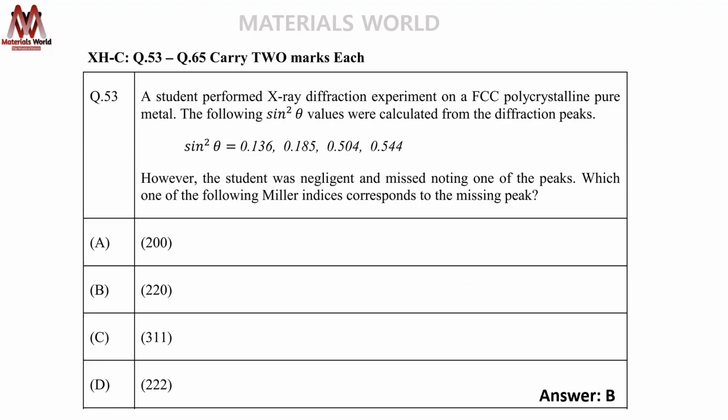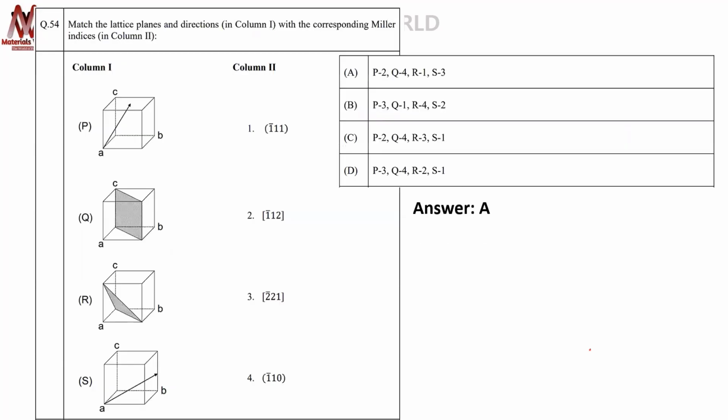If it is matching with 3, 4, 8, 11, then it will be FCC. Then you can take individual theta value, and then you can take other lambda given, and you can calculate A also. And if you know A, you know which material this is, because A is well known in the database, right? So this is how manually we do.